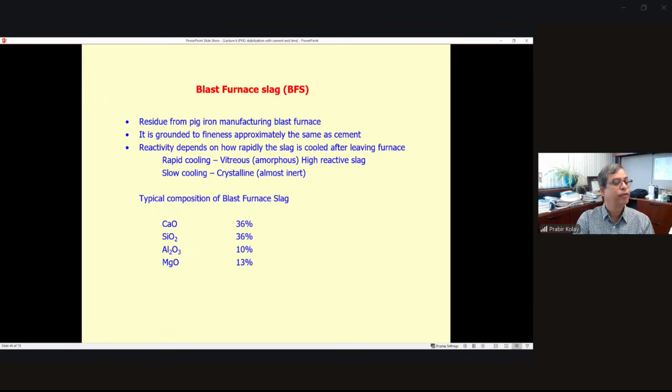These days, the instrument will give you this automatically. So basically, with XRF you get the chemical composition, and then what are the different mineral forms? How do you know the crystalline and amorphous? From the X-ray diffraction analysis, you can find out. X-ray diffraction analysis also will tell you what type of mineral forms after this chemical reaction. That is the test you need to do, and then also do scanning electron microscope to see the microstructures. There are two tests we generally do: X-ray diffraction, and scanning electron microscope.